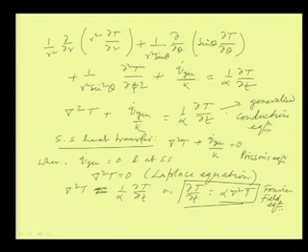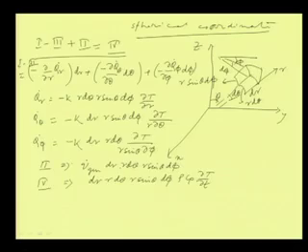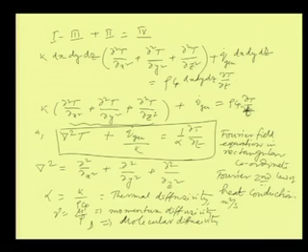When there is a heat generation term but it is at steady state, it is called Poisson's equation, and when there is no heat generation and steady state, then grad square T equal to 0, this is called Laplace equation. If we see the whole equation without the generation term, when this is equal to 0, then it is called Fourier equation in rectangular coordinates, or Fourier second law of heat conduction.